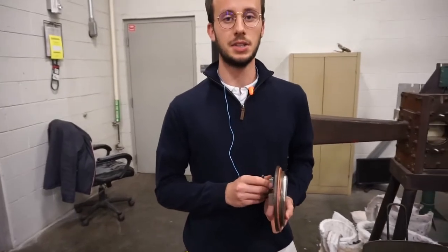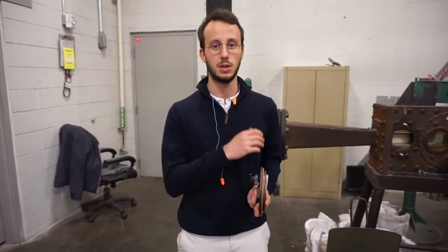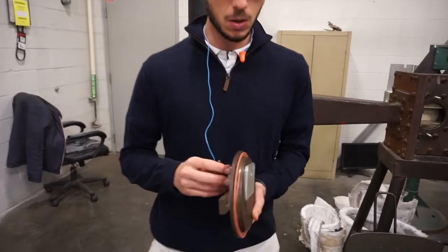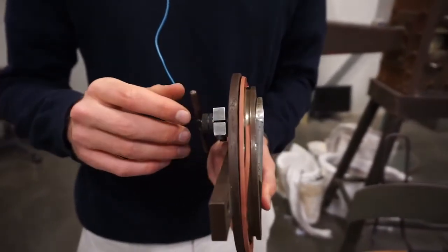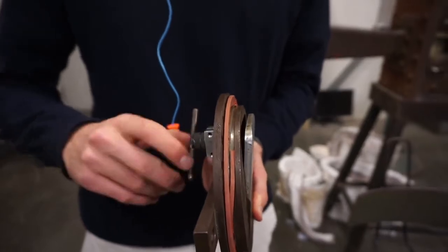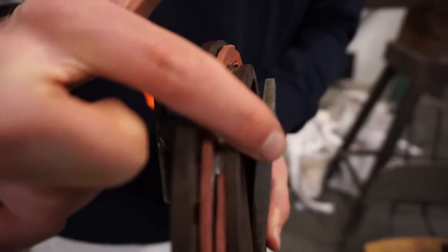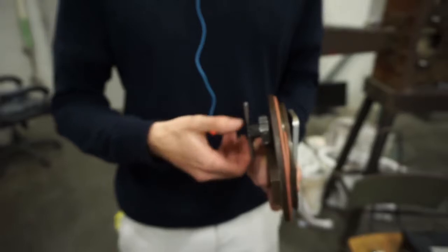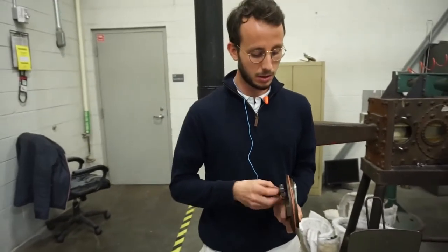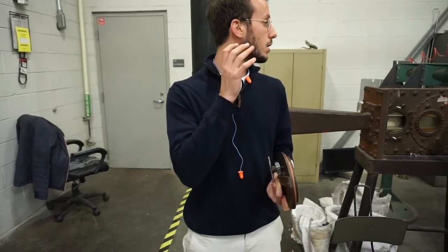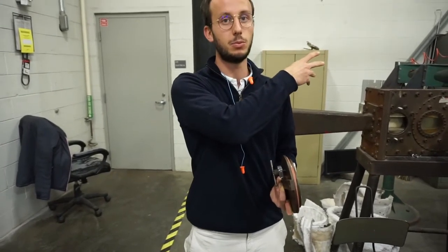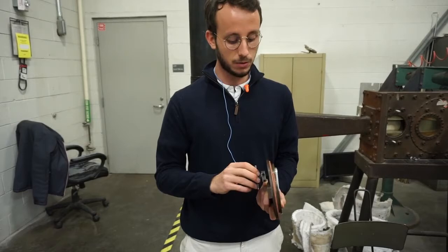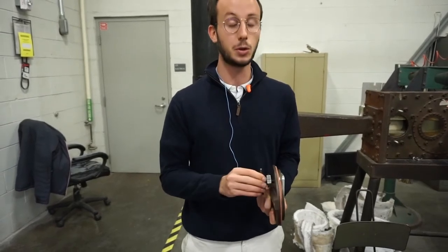Now we've done stagnation and static pressures with the pitot probe inside the blowdown tunnel. We'll use the variable cross-sectional area diffuser right here. We'll modify the cross-sectional area inside the test section by screwing right here. It will increase the angle of the plate right here and reduce the cross-sectional area inside the test section. While running the experiment, we'll increase the pressure to the same 14 psi we used previously, and we want to find a point where we feel the shock on the screw right here.